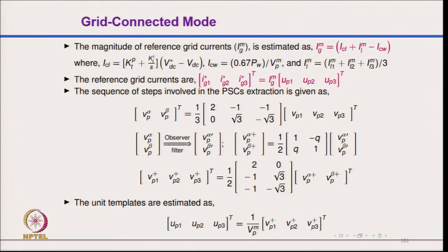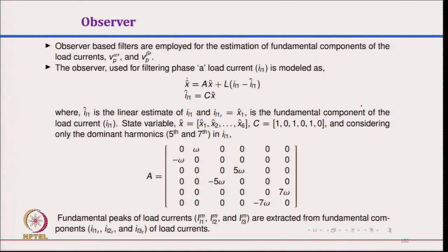So, typically the algorithm that you have is a DC link voltage controller using a PI controller, then you have a component corresponding to the wind generation. This is for load compensation, and that is your reference grid current. Multiplying by the template, you get the 3-phase current. These are the template calculations from the sensed voltage, phase voltage, and line voltage.